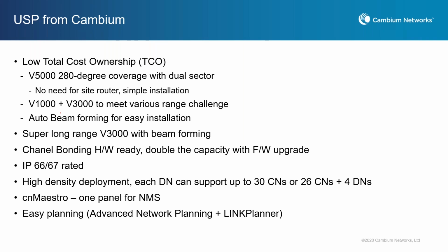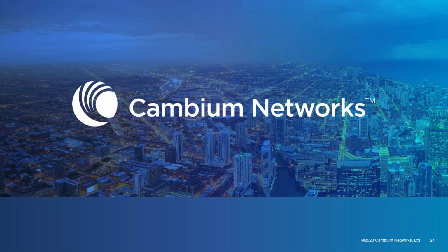So Alan, first question for you: is it accurate to assume that 802.11ad was a best effort connection and 802.11ay is a dedicated SLA? Is that an accurate statement? Yes, the 11ad product, because it's using CSMA for channel access, is for low density, where you have less conflict, so you have pretty good performance.